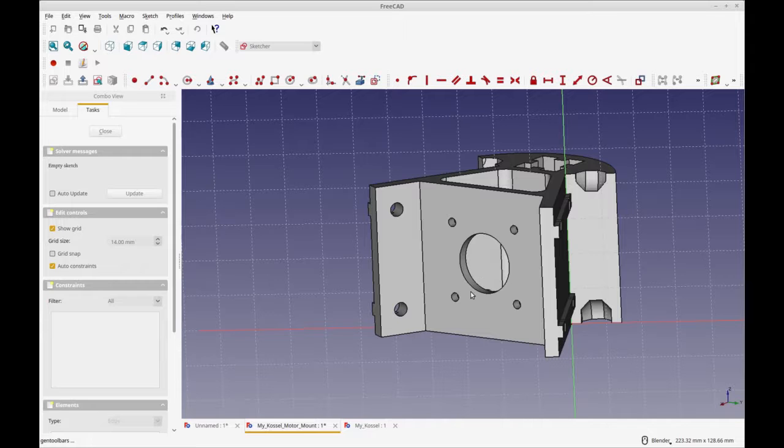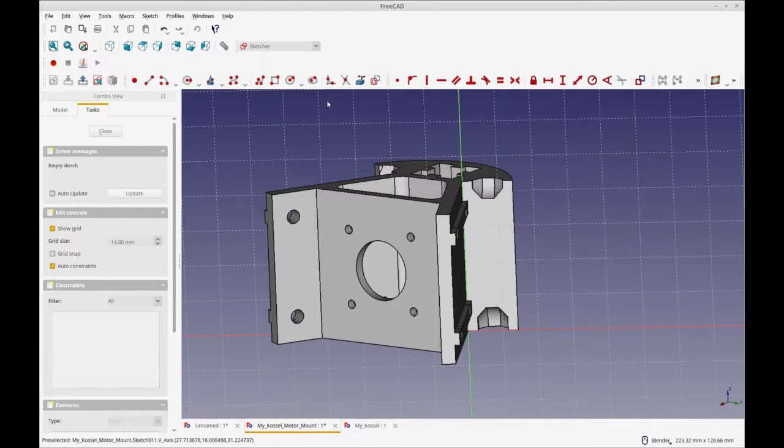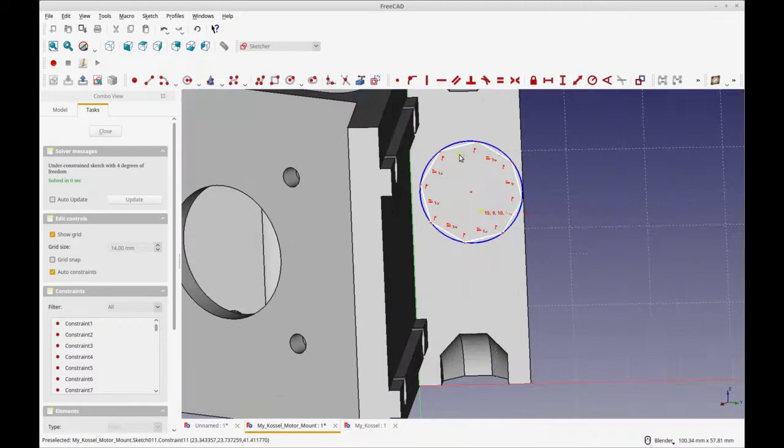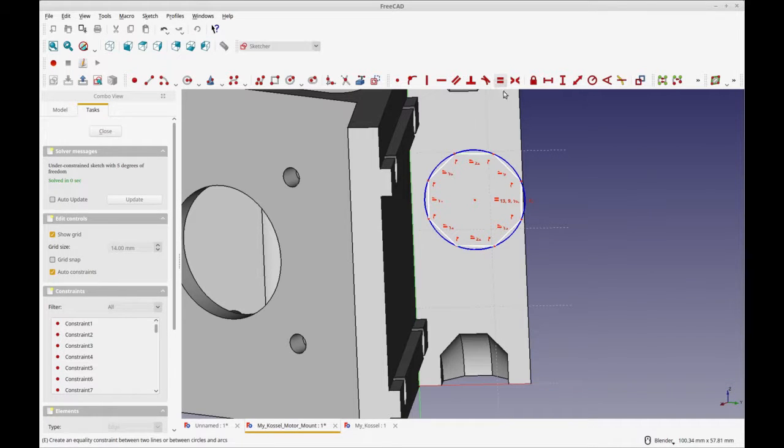And sometimes I have to reorient to see where I'm at. It's going to be an octagon, and that'll be added somewhere in the center here. Oop, a little bit big. Let's make it smaller. Move it, and we're going to just make one of these vertical. And let's zoom up. So we're going to remove the equality. We're going to turn this a little bit so we have an easier one to work on. You'll see why. I don't want to have to fiddle through all of these. So I'm just going to remove the equality constraint on this and on this, and then I'm going to reset them just to be only equal to each other.